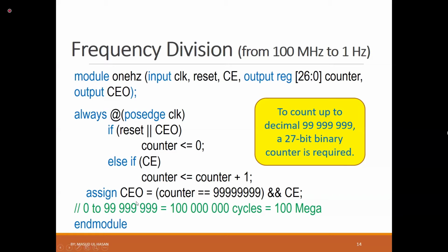Okay, now you are right. It is clock gating, but not this different clock is provided to different circuits in our main circuit. We will divide this one time and then we will provide it to all of the components in our circuit. So all of the components will be synchronized with this clock, right? So this will be available at the same tick of this clock, our 1 hertz clock. At the same tick of this clock, everything will work.